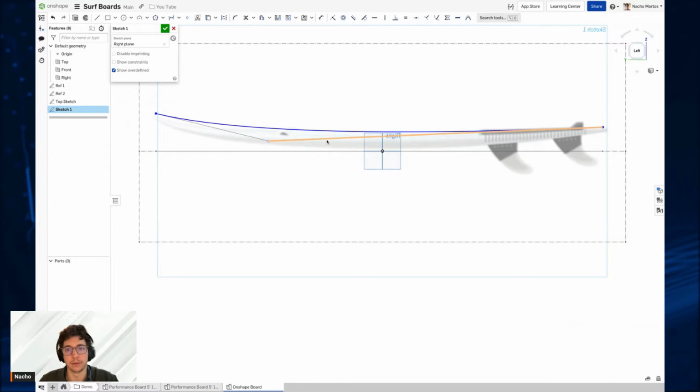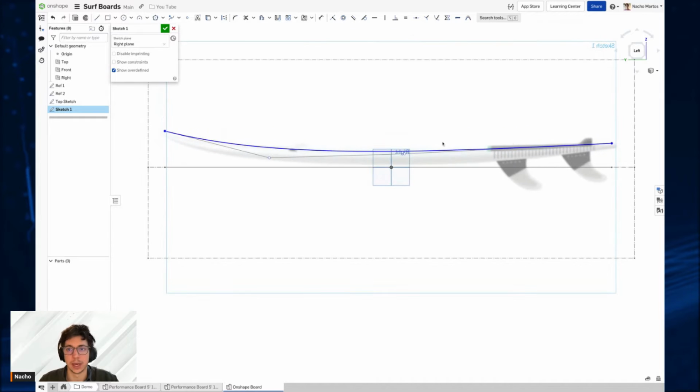If you find yourself wanting to change this geometry a little bit more, feel free to add another spline control point to your Bezier, and you can see how you do that. So I can add another spline point here, and that's going to give me a new area of control. That's still a pretty nice curve, so we don't really have to worry too much. That looks pretty good to me.